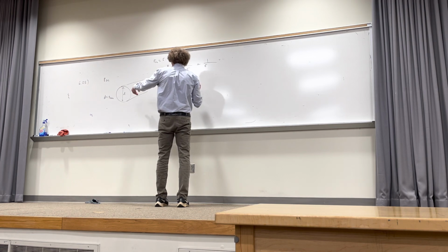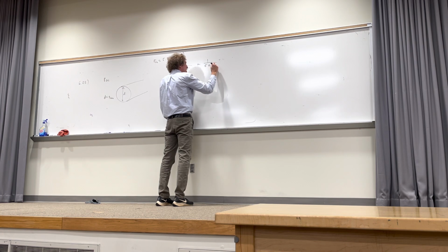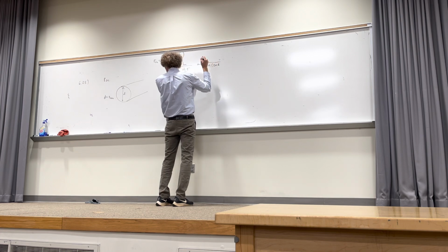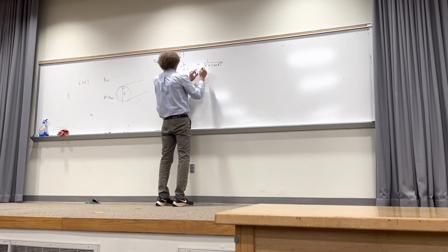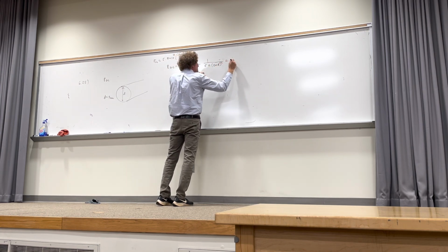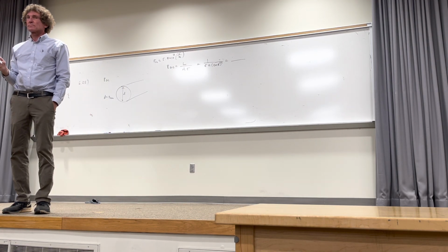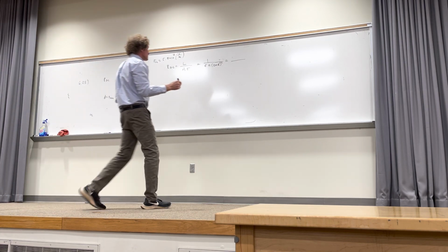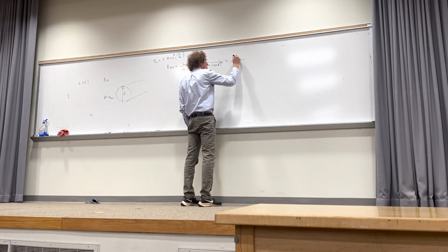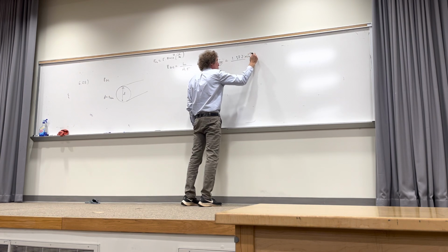So I'll take the radius as 2 millimeters. So it's going to be pi times 2 times 10 to the minus, see, that's millimeters, so it's minus 3 squared. And sigma here is 5.8 times 10 to the 7th. Can you just tell me what that is? It's going to be very small. 1.372 times 10 to the minus 3 ohms per meter.